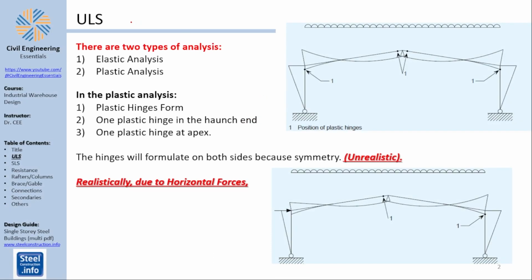Alright, so when you deal with your ultimate limit states, you have two possibilities for analysis: an elastic analysis and a plastic analysis. Now I know that the ultimate limit state happens when the material starts to fail at the ultimate stresses, which means you are way beyond your yield stress. But as we'll see during this lecture, the Eurocode as well as the American codes actually allow you to use the elastic analysis and design using those results in the ultimate, beyond-yielding stress range.